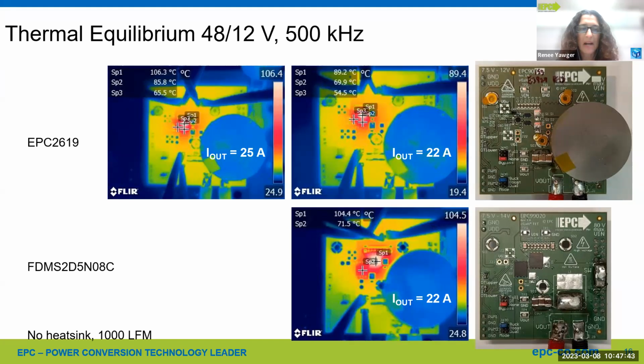Okay. This one, I think you addressed a lot of these, but I just want to give you a chance in case you want to add anything. So the question was, what challenges do most people face while designing with GaN, and how to tackle them? I would say, if you look at a data sheet for a GaN FET, it looks very similar to a silicon FET. The charts are the same, the things are the same, the numbers change. And I think that's basically the challenge. The actual numbers are changing.